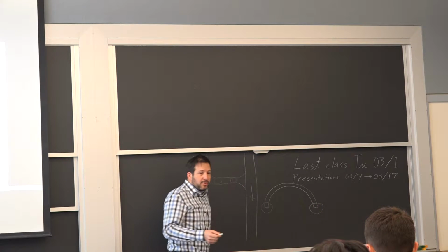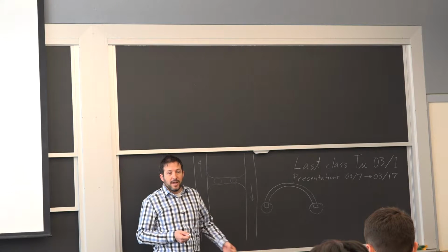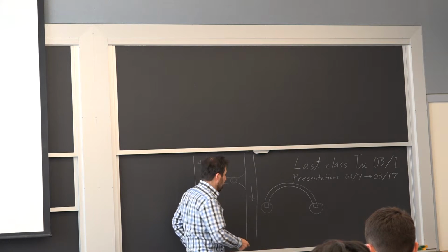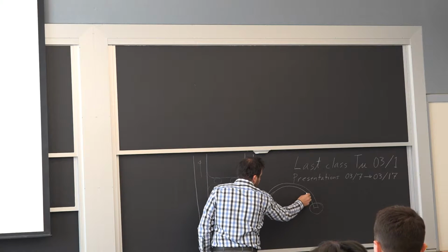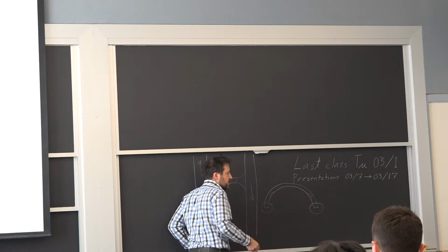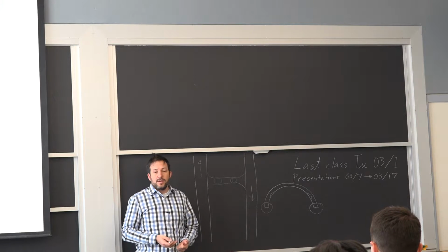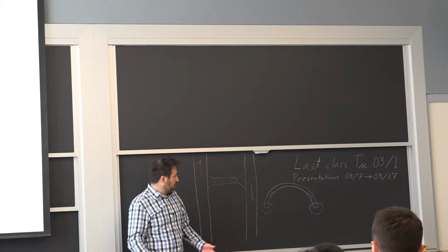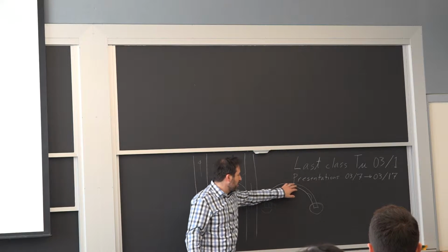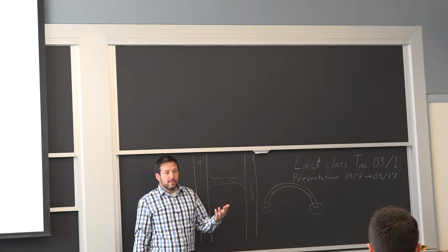I would rather not have a lot of deformation going on at that corner. So what if I make the dome thinner somewhere in the middle, same principle, so if it has to absorb some energy, and that could even be differential thermal expansion from summer to winter. If you have a way that you can accommodate for it in the primary structure, then you'll win.